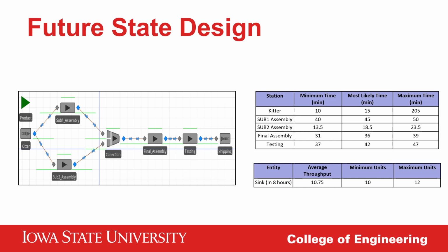The other thing we wanted to change, which is probably even more important towards implementing a one-piece flow system, is the pre-painting and outsourcing of painting for some of the components they use in their assembly. A painted component has to be dried, and it has to get painted on the floor, and that creates a buffer between when it can be painted and when it can go into production, which throws off a one-piece flow system. So we're proposing that our client outsource all of their painted components instead of painting them in-house.